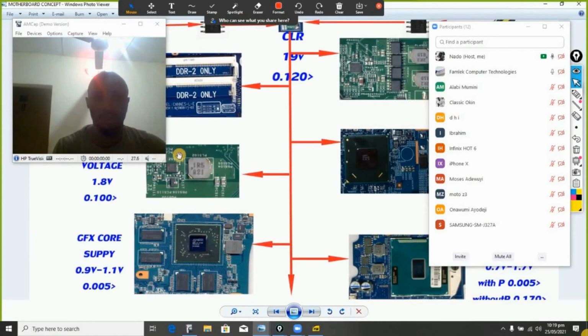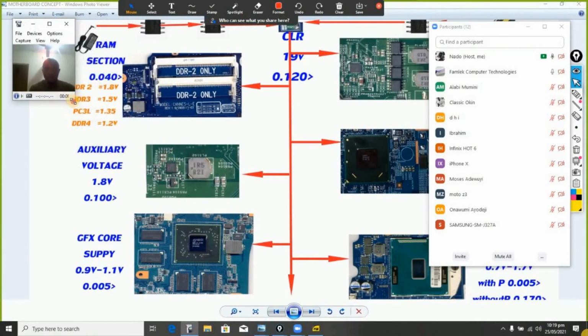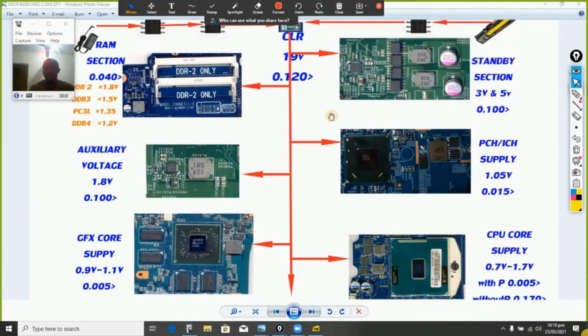Now, when I was explaining at the beginning, when I was talking about why, when, and how, I said these other sections can't work on a high voltage. That is why we need this one to power the rest. At the same time, I said 19 volts, once it is generated, is going everywhere on the motherboard, and this is the part here that we can all see is going to the motherboard. What happened? So is it convincing or not?